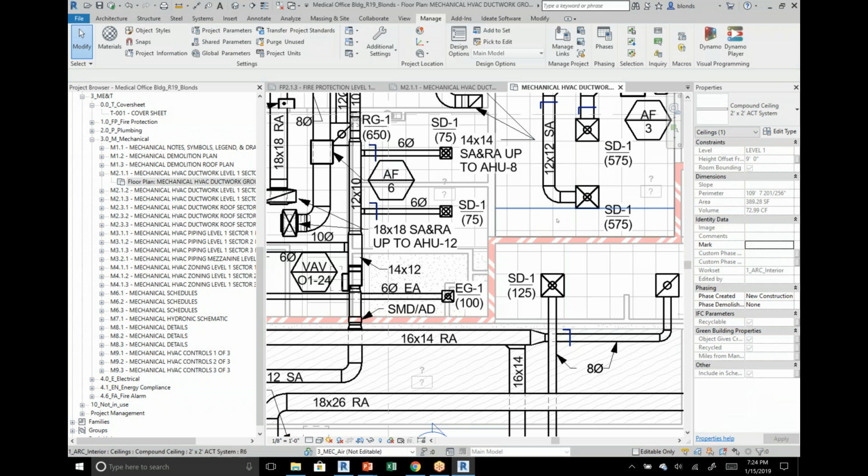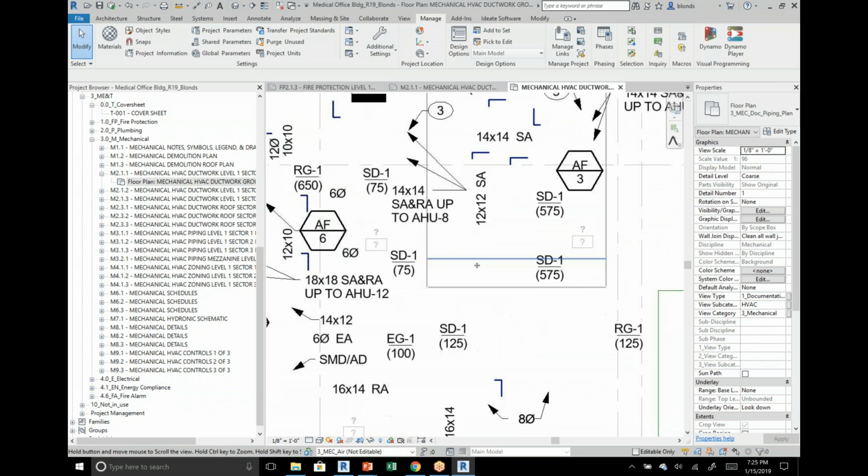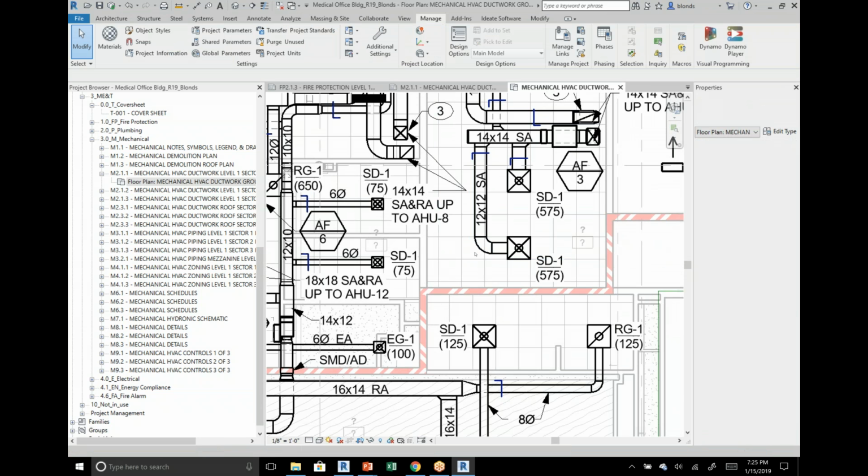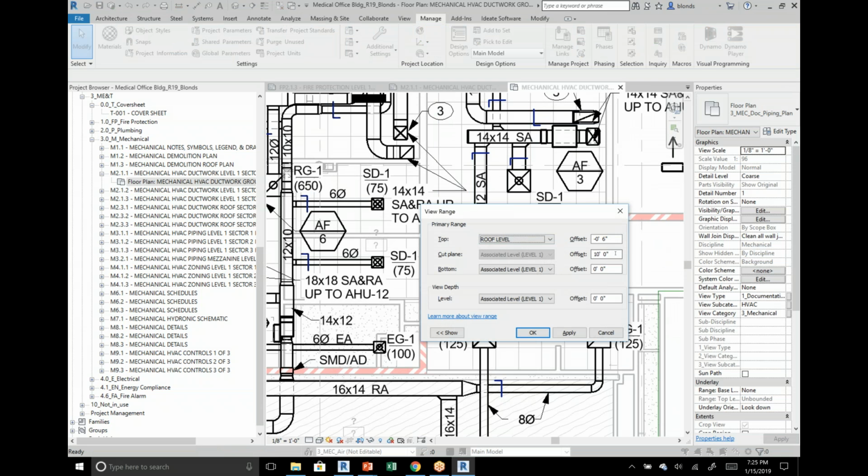So while we have the ceiling showing up, this is actually a floor plan view with a modified view range that has the cut plane going above the ceiling so it can be seen, since the cut plane is what's actively showing us the architectural background. And again, this is a slight abuse to kind of leverage having our hidden lines work for us.